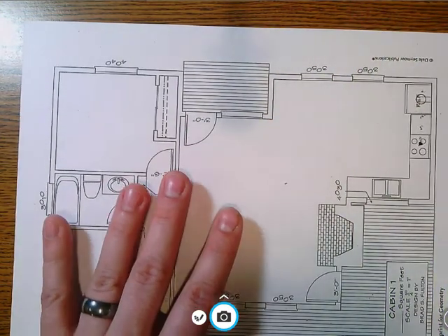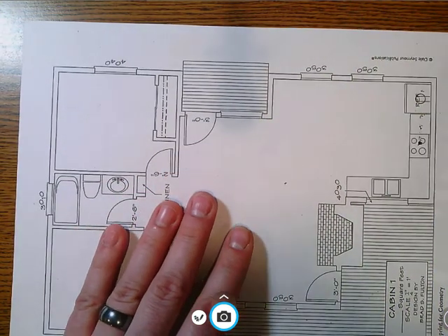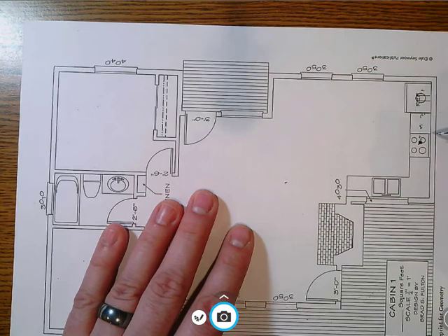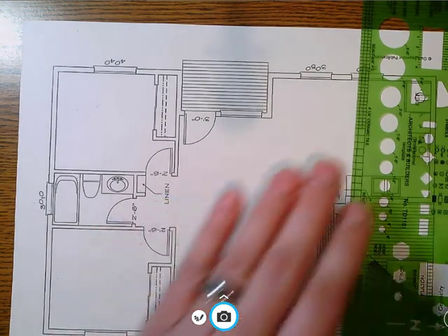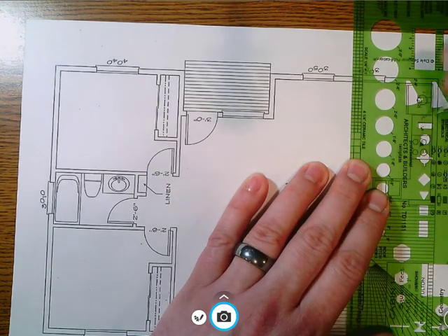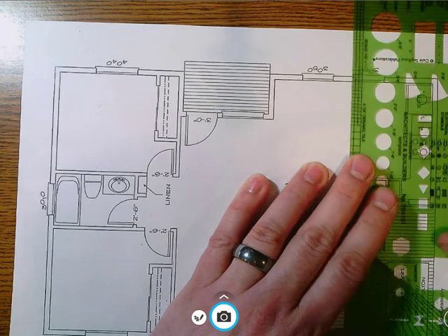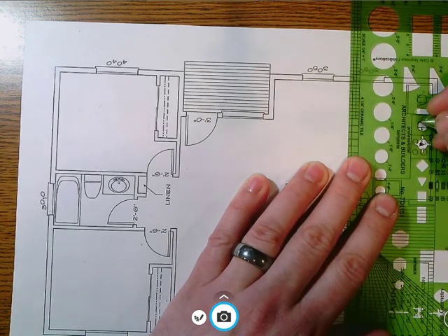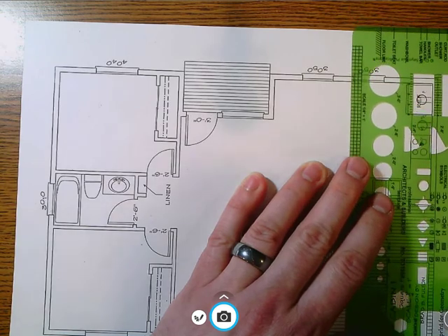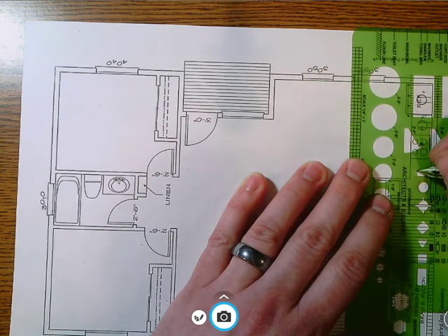So that's an outlet. Now remember, for countertops, we've talked about this as well, no space along a countertop can be further than 2 feet away from an outlet. So all this countertop that I have here, I'm going to need to place some outlets. This is so we have access to electrical wiring for coffee pots, blenders, food processors, whatever else you may have. So let's start laying out all of that.